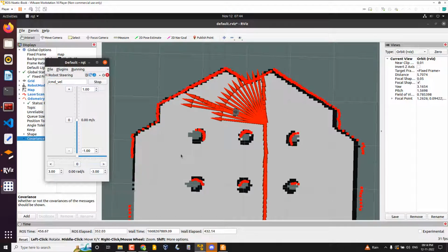But if it is an environment with a lot of stuff, then you can memorize the things based on the features. So that concept, I think we can apply to robots as well, in the SLAM algorithm context. If there are obstacles, the robot can detect them using the range sensors or the laser scans, and then that detection and those features can be used in the SLAM algorithm, and we can create the map, something like that.